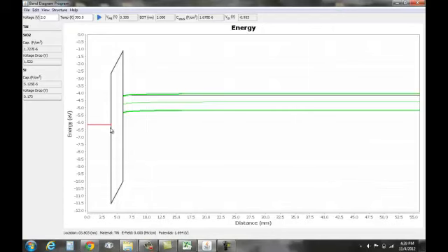As I move my cursor, the numbers in the text are no longer frozen. Moving over to the leftmost panel, I can see that there are the three materials: titanium nitride, silicon dioxide, and silicon. The parameters given for silicon dioxide and silicon are the capacitance of the material and the voltage drop across the material. The reason that titanium nitride doesn't have this information is because it's a metal, so it doesn't hold an electric field. Therefore, there's no potential drop or capacitance across it.